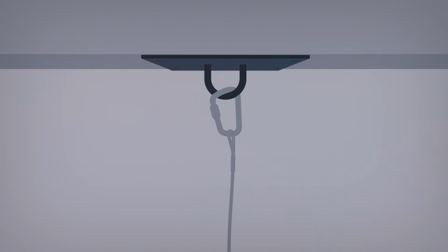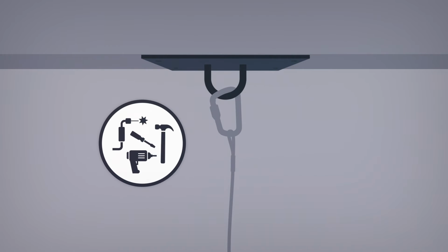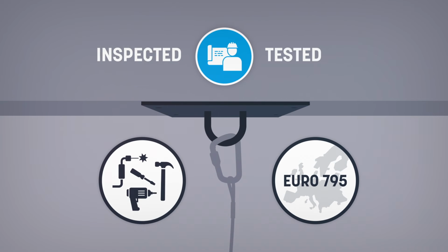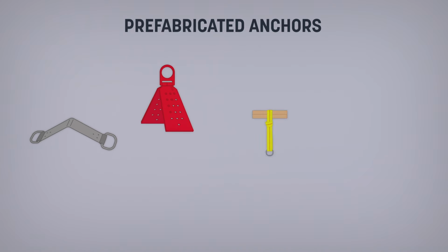It's possible to use a custom-made anchor system or one certified to another standard. Before its first use, it must be inspected and tested by an engineer to verify that the design and installation are compliant. There are several models of prefabricated anchors.